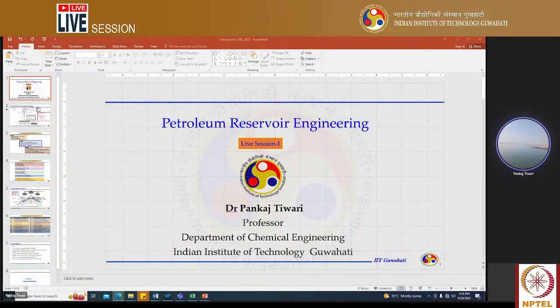So, in this case, if you start with Darcy's law in the appropriate unit system for the radial flow system, you should be able to get the value of permeability that is asked in this question. So you just do the Darcy law calculation with the information provided to you. The missing part in that expression is permeability, because flow rate and pressure difference are given to you. You should be able to calculate the value of permeability.